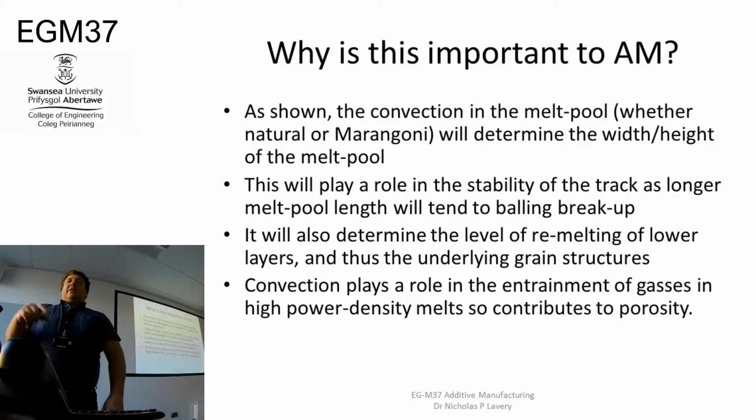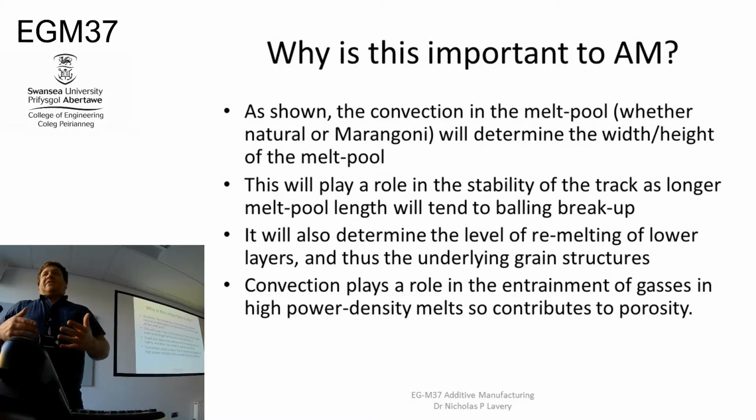And obviously the convection does have a role with the gases in how much can get entrained. So when you're at that very high power density where you're starting to get keyhole and you've got gases coming in, that convection is also going to determine how much extra porosity gets formed.